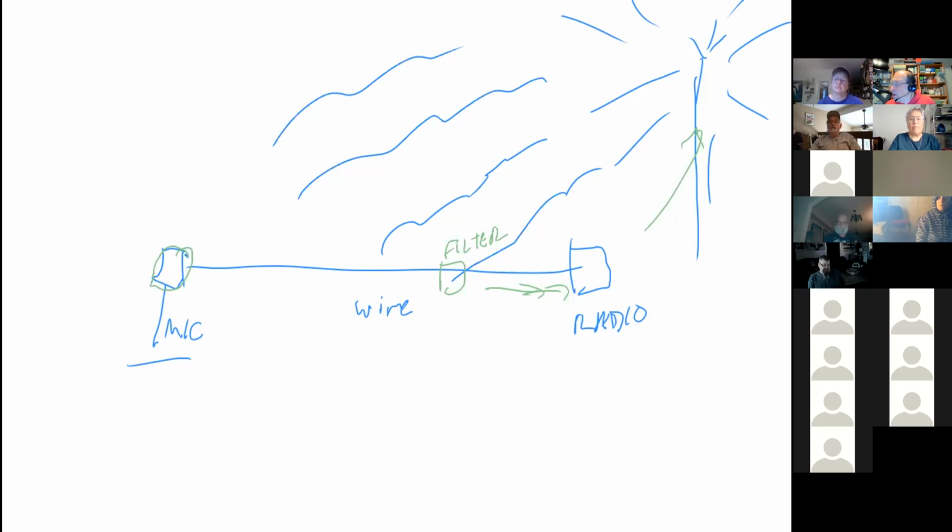Sometimes we actually take our entire cable, with shield and all, and run it through a ferrite choke, which basically collects the RF energy on the outside and causes it to make a magnetic field that then gets burned up as heat in the choke, which is something we're going to get to also. If you're told your FM handheld or mobile transceiver is over deviating, you back away from the microphone. Okay, so now we're doing meters, testing, and things like that. I'm going to bring up a picture of that while we're talking about it.